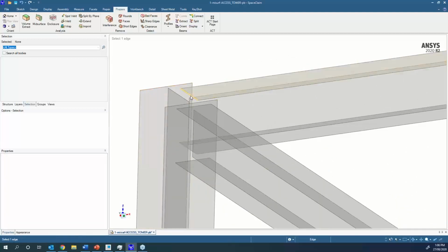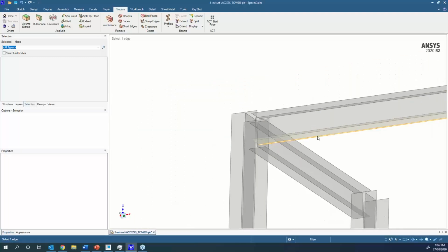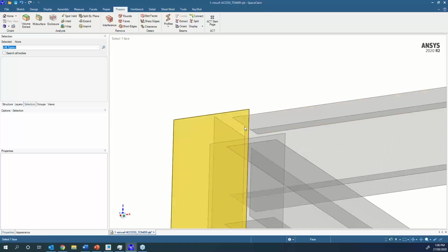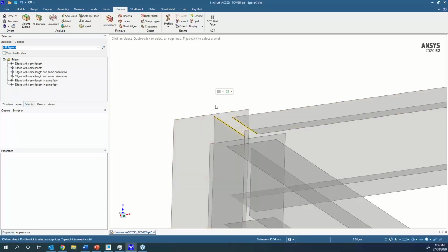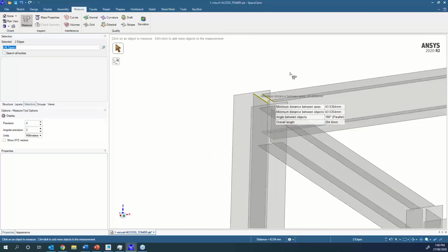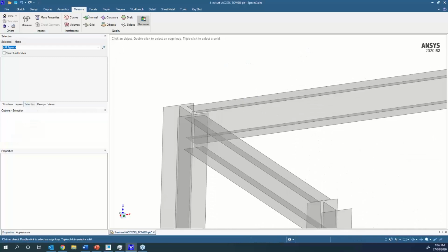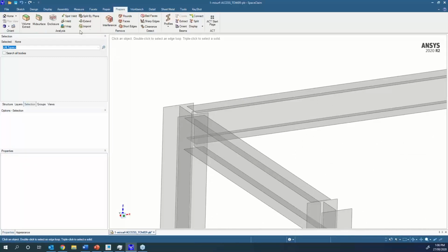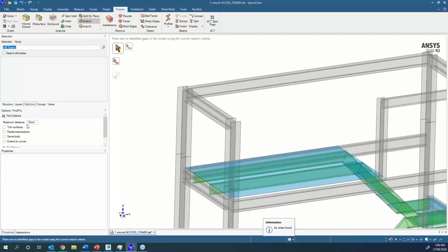Now that's a pretty common thing to happen when you reduce 3D geometry down to 2D. So there's the tools here to help with all that as well. So again, I'm just going to check distances, and I go to my measure tool here. This will probe the distance that we're looking to close up. That's 43 mil. So if I go back to the Prepare tab and I pick the Extend option here, this is asking for a max distance.